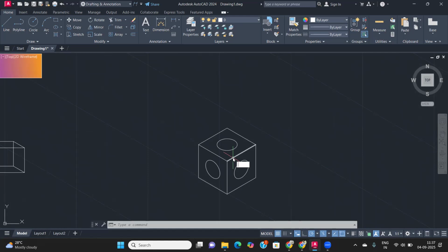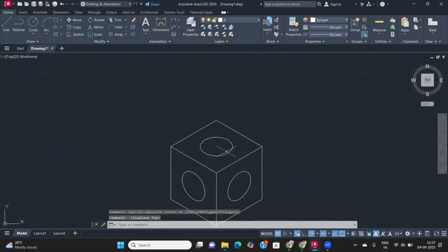Suppose first of all, press F5 to change the face, so first it is the top face, because I want to show the chimney on the top side, and then use the copy command. Right, I copy this circle, enter, and I select the center point. Remember that this is your straight line. I take 100 distance, right? And then I want to show the chimney type. This does not look like a chimney type.